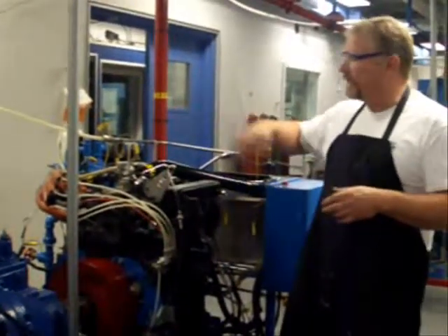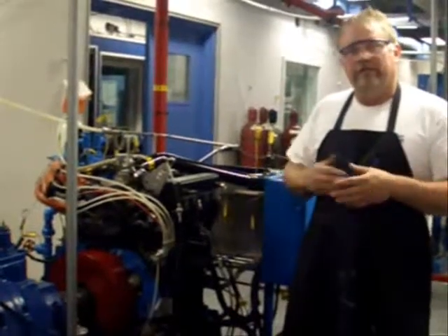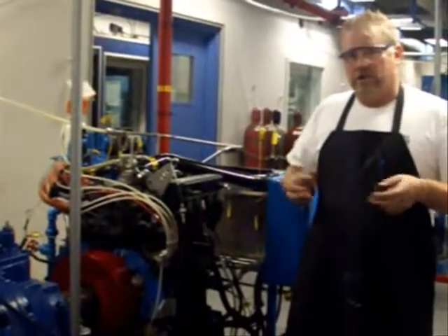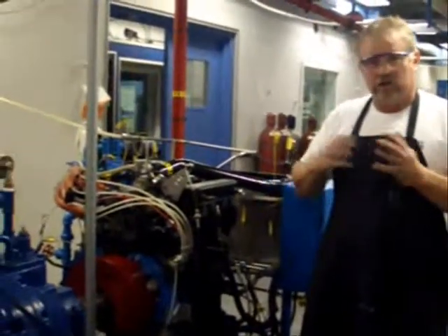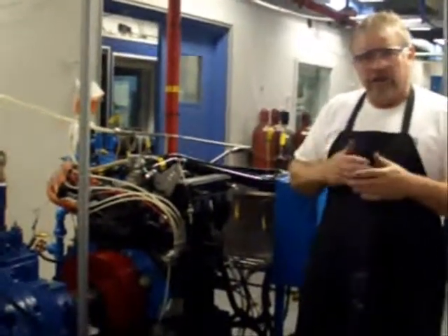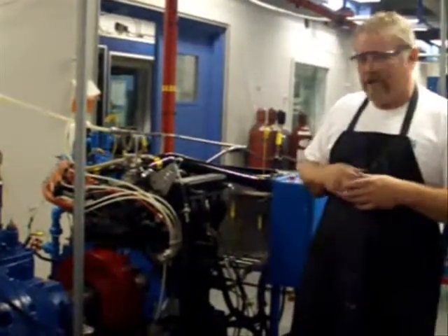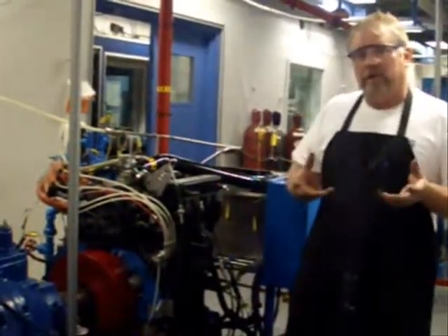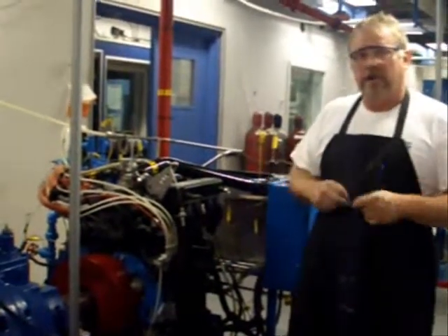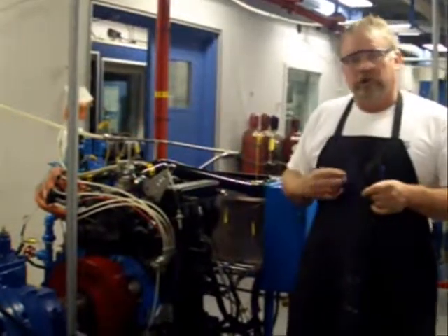We're also looking at the coolant and water flow of the engine. An internal combustion engine makes a lot of heat. There's a lot of frictional loss, a lot of parasitic loss on the combustion process, and the frictional loss of the metal components working against each other. So because of all that built up heat, we need to cool the engine. And by doing that, we have a recirculating coolant system.